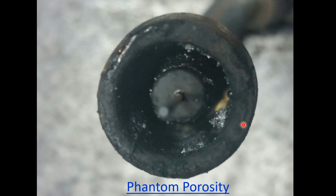I'm telling you this because I need you to start paying attention to when the robot reams and this porosity. Because if this porosity shows up at the last 2 cycles of your cycle between reaming, and then it goes away immediately after it goes for a ream, this is the problem. This happens so often, I really needed to make sure I bring it out there.